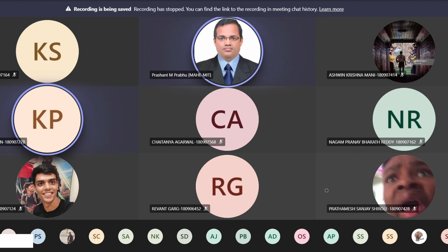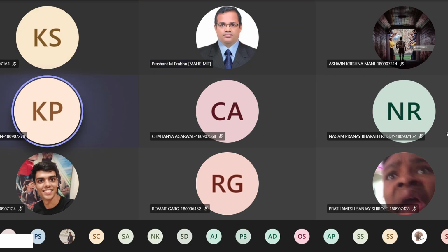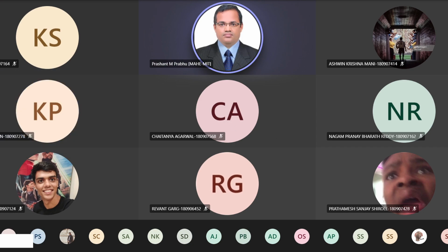Yeah. So realistically, when we use delta modulation or this adaptive delta modulation, how much faster do we have to sample the data compared to say the Nyquist rate? See now, suppose I have a 1 kilohertz signal. Okay, message signal I have a 1 kilohertz, right? I need to sample it at the rate much greater than Nyquist. What is the Nyquist rate?